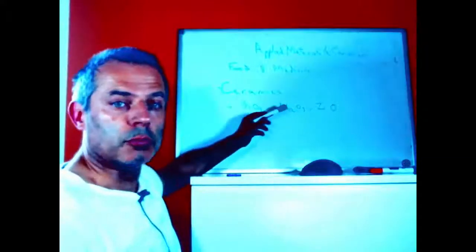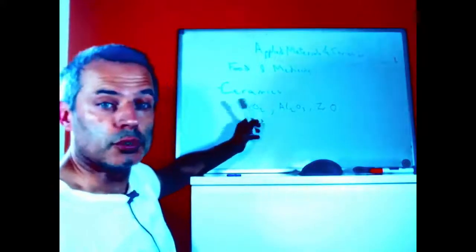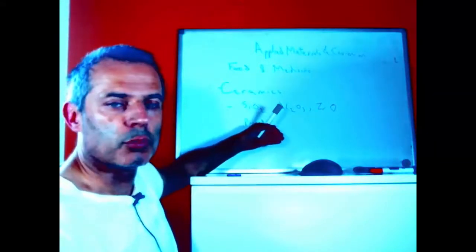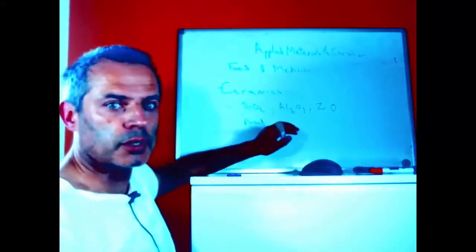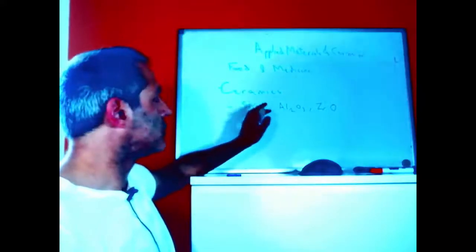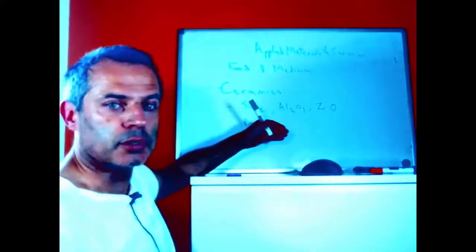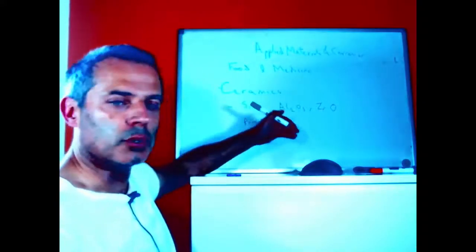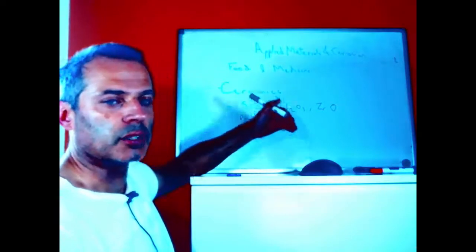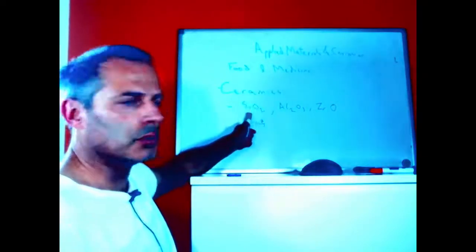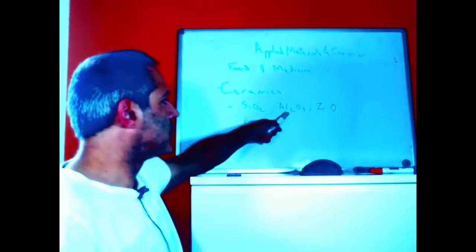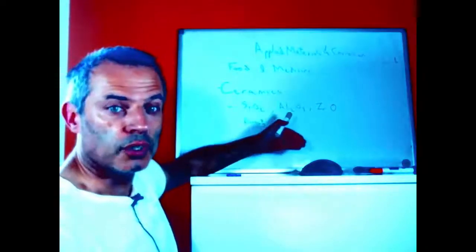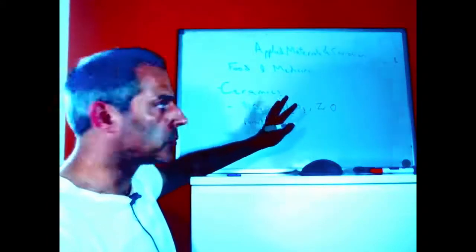The other advantage that we might want, or the other thing that we might want to do, is grind some food or grind some material for use in medicine. And there we have a problem with loss of particles and self lubrication. So we would like our grinding head to not lose too much material that can cause problems. And that's good if we use a ceramic, particularly an aluminium oxide ceramic, because aluminium oxide particles are not going to do very much if they get lost, as long as they're not too sharp.